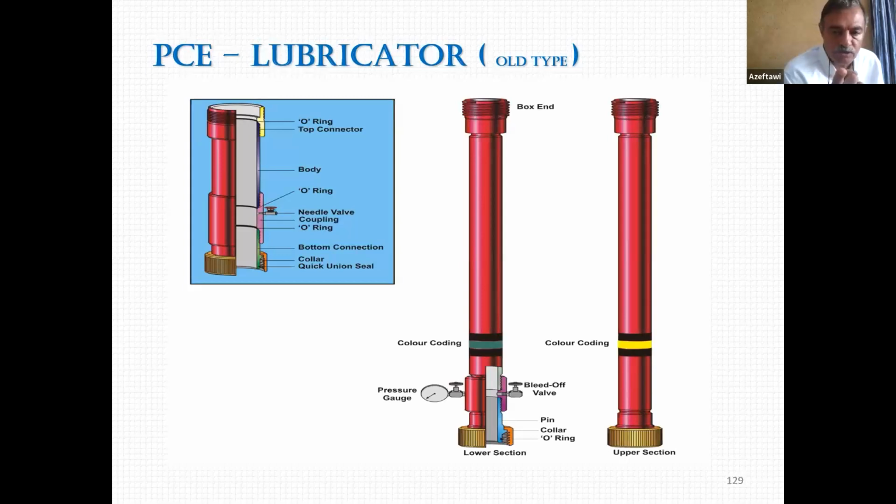This lubricator you see in front of you is obsolete. This one was banned years ago because it is not integral. What do I mean by integral? One piece. It has to be one piece. What you see in front of you is not one piece.